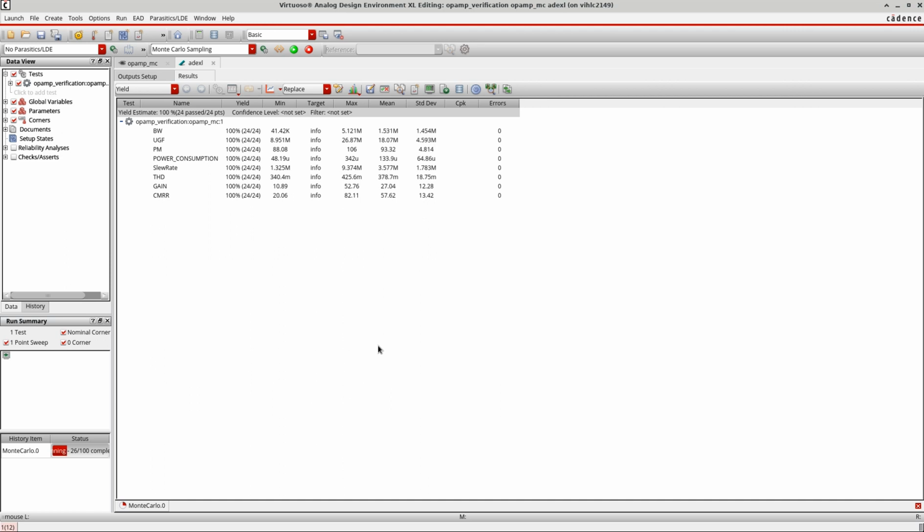So here, as you see, I defined all those in the calculator, then I can display it. If you use a waveform, like the AC response, you won't get any number here because it's a waveform, so you don't get any Monte Carlo. So remember, whenever you want to do a Monte Carlo simulation, you need to define that in the calculator.